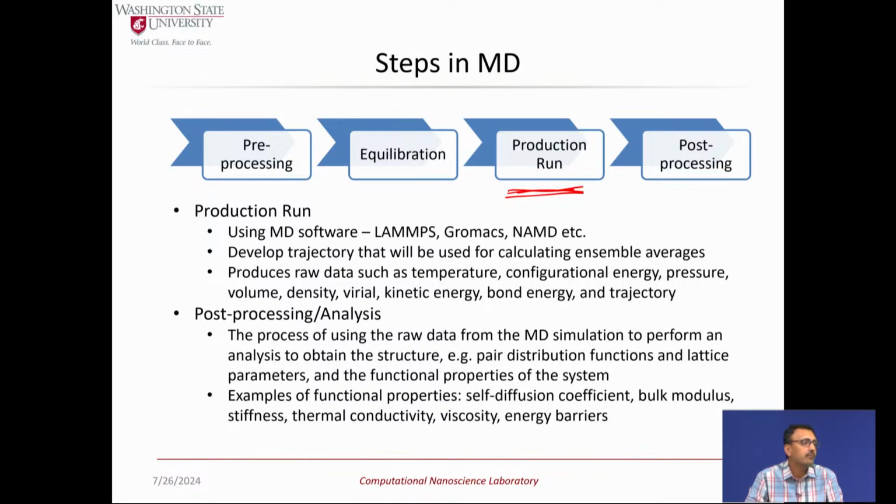No, I mean, I have a crystal structure with a particular lattice parameter. I want to know the properties of that particular lattice structure, with specific lattice parameters. So without doing the minimization, because if I do the minimization, the structure will be relaxed and it will try to get the equilibrated lattice parameters. Right, but even if you don't do the static energy minimization, even if you just ran an MD simulation, it will try to converge to the same.